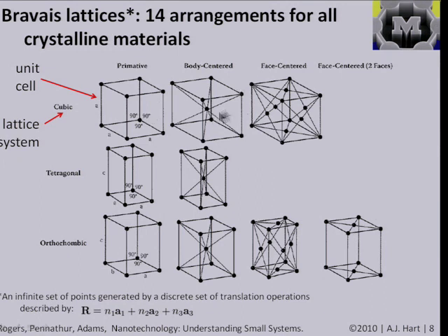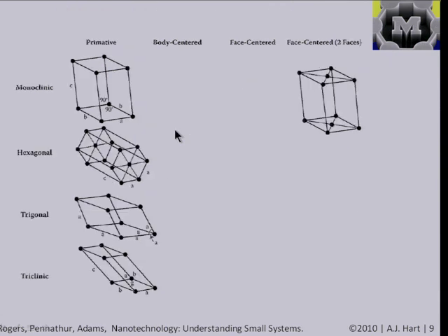And then there's body-centered cubic and face-centered cubic, where in body-centered cubic you have an atom at the center, and that's sort of all you add here. And in face-centered cubic you don't have an atom at the center, but you have atoms at the faces. So in each of these cases, the unit cell would have a different number of atoms. And we're not going to go through these, but you might hear these terms as we go on, and you could look back and look at these structures. And there are also more complex or intricate organizations of atoms that satisfy this Bravais definition, and this completes the set of 14 that exist in this way.